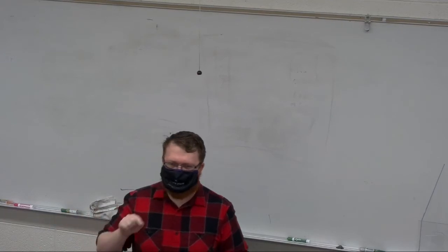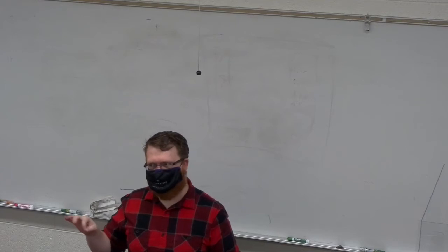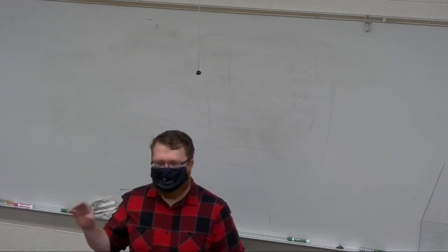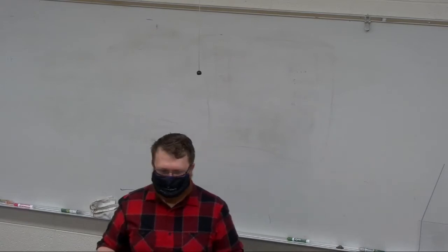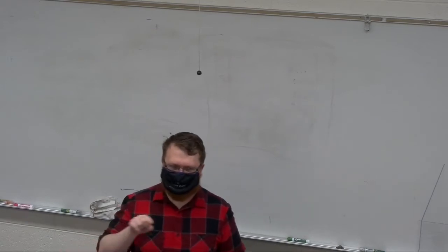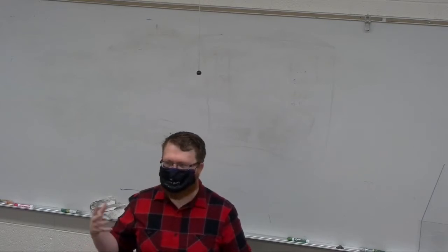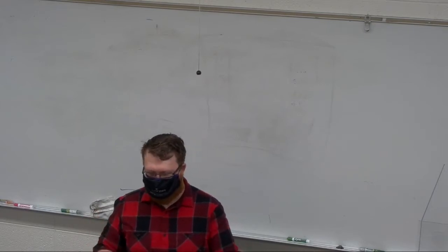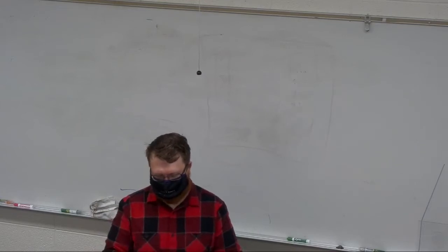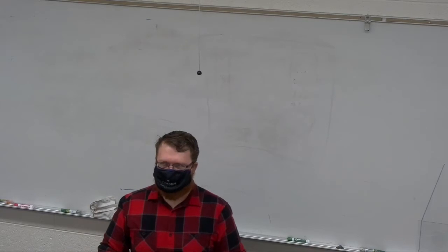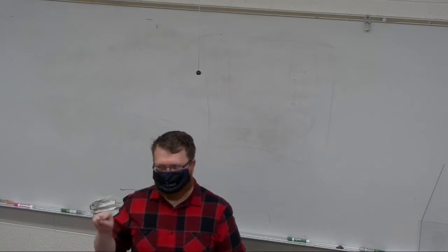PLAs are programmable logic arrays, and PALs are programmable array logic. Silly reuse of names, but it makes a little bit of sense because a PAL is really just a specific type of PLA. And we'll get into what that means and why later. But that's all we're looking to get through today, is PLAs and PALs, which are both a subcategory of SPLDs.